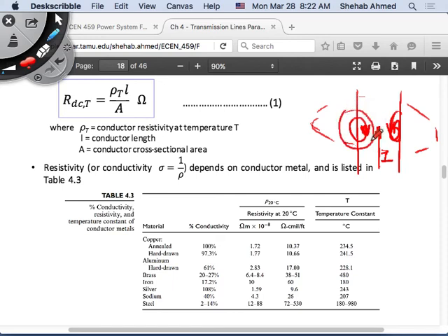These eddy currents will typically oppose the current that originally created the magnetic field. So if you look at the sum of the currents in this conductor's cross-section area, you will see that these eddy currents are going this way, and this main current is going this way. What happens is that there's a decrease in current density in the center of the conductor, right?